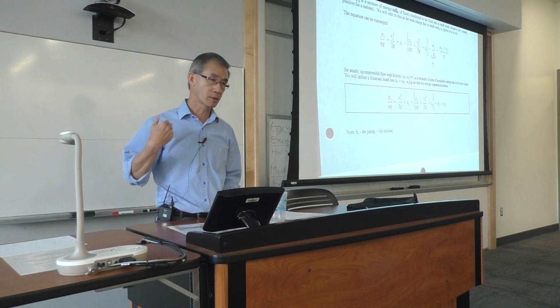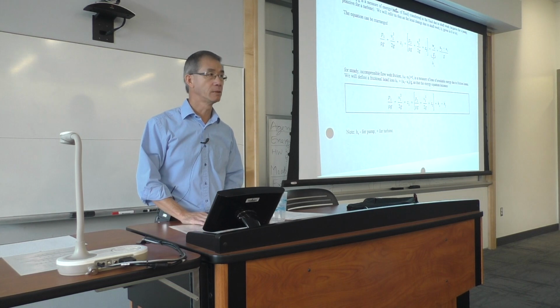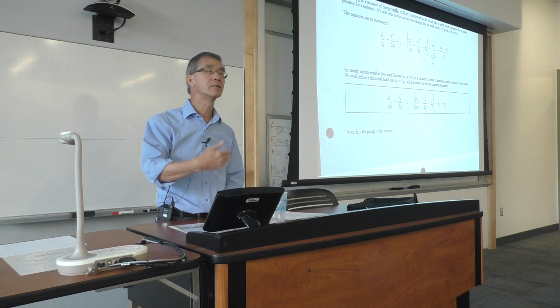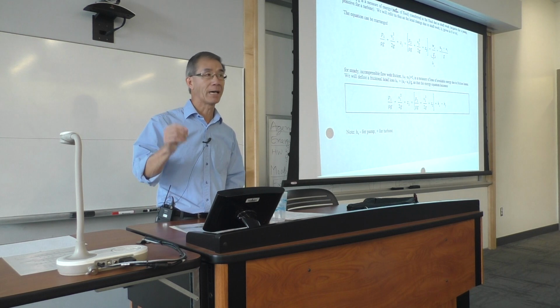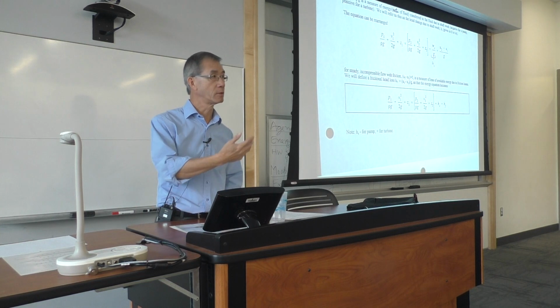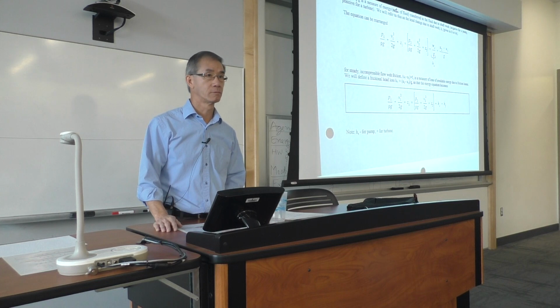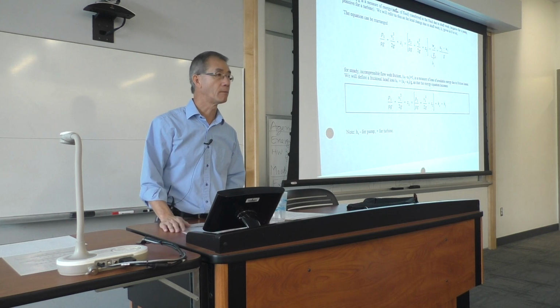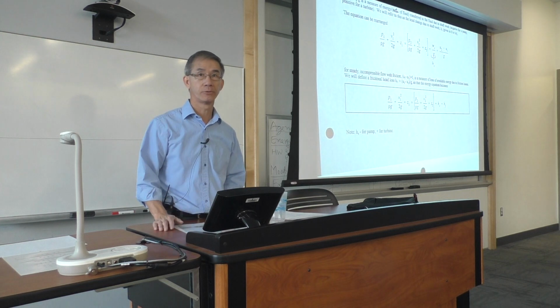And if it's a turbine, it's the opposite. So that head has some really important implication. It is an indirect reflection of how much work or energy or power can be transferred to the fluid. And that's why in layman's terms, in sales of pumps, they don't use kilowatt or horsepower of the pump. That's actually very odd. You just talk about head. Okay? And so that's why people use that.